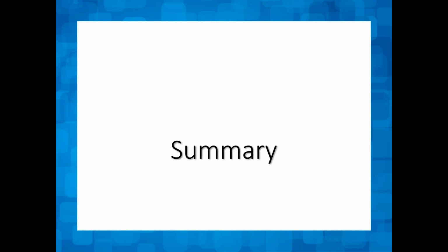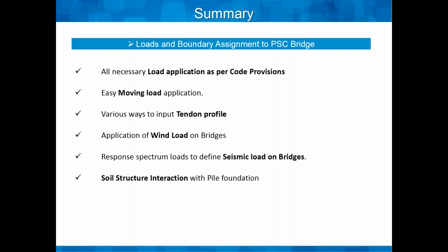Let us summarize today's session. So in MIDAS Civil today, we saw how to apply the boundary conditions and loads on a PSC bridge. There are all necessary load applications as per code provisions available in the software. You can apply moving loads very easily. No need to manually apply the moving loads using static loads and then create manually the envelopes and then take out the critical results, which is quite time consuming. So it's much easier in moving loads.